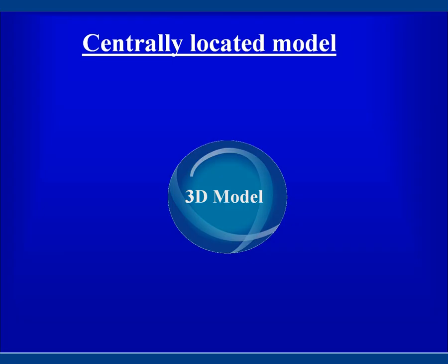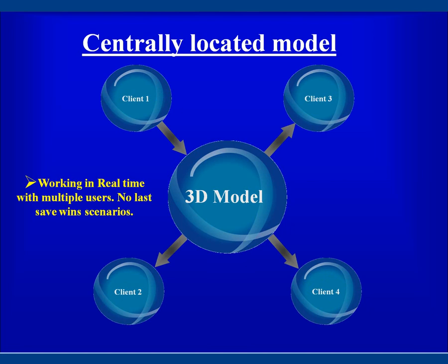When in the modeling module of SDS2, when a user adds, modifies, or processes members, all the users on the project will instantaneously see the results in real time. There's no saving of these operations required. The only operation that requires a save in the modeling module is the creation of erection views, which are snapshots used to create 2D erection or placement drawings.